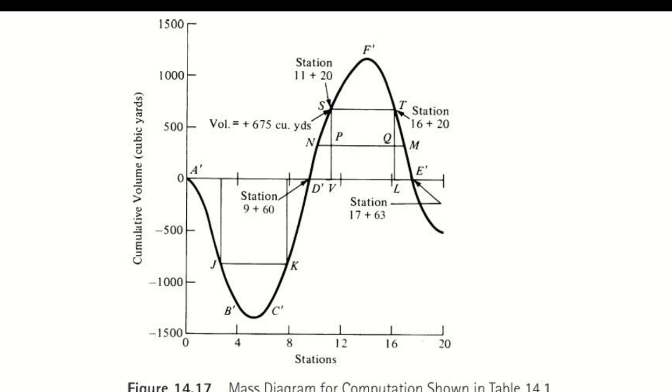They are saying x is 9 plus 60 stations. But no equation can give you a value like 9 plus 60. So this equation will give me 9 and 60? Could be, makes sense, because each station is 100, right? But I did something when I wrote the values, so it will not give me 960. To get 960, I should put x1 and x2 differently.